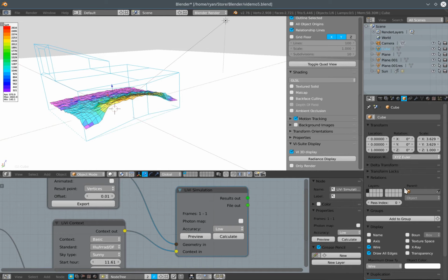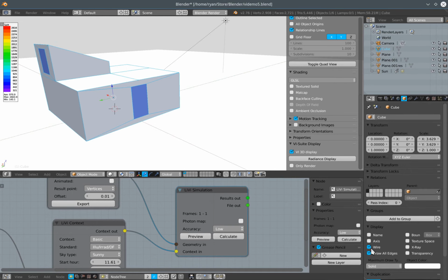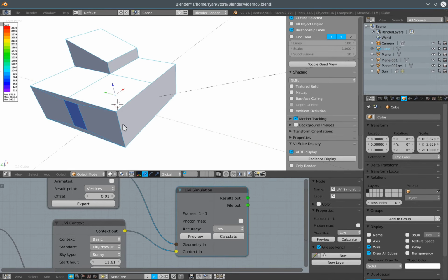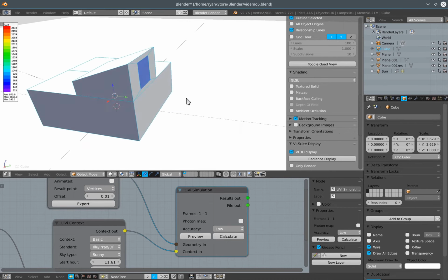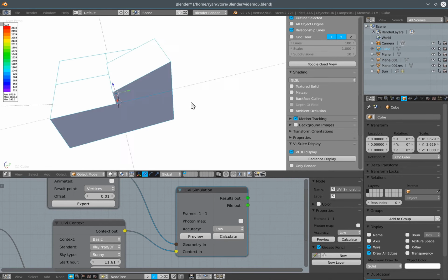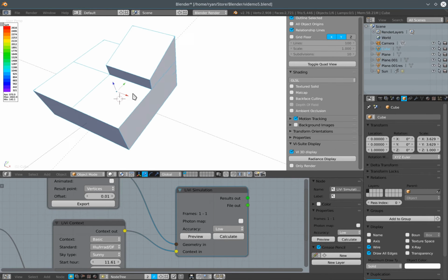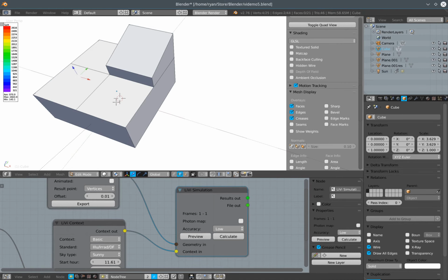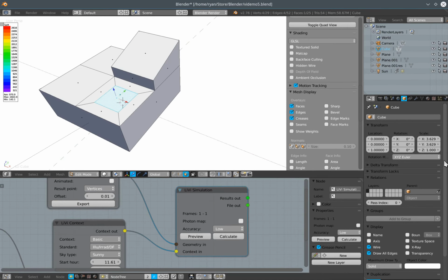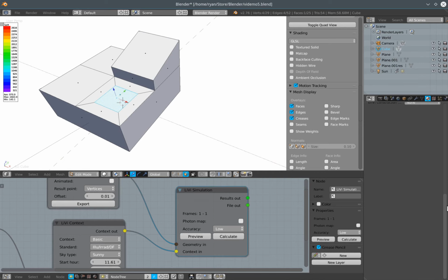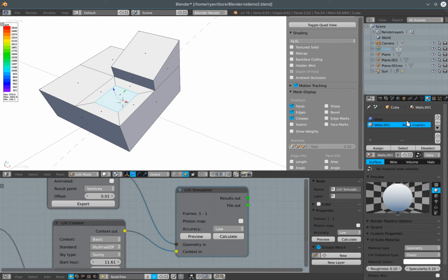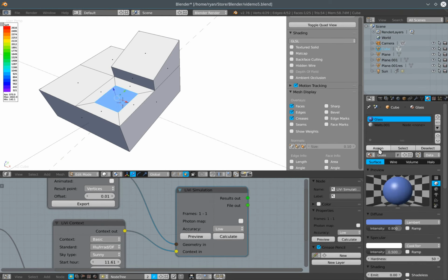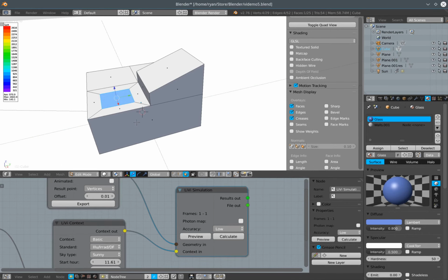So if I just put that building back in, I've now got a much narrower window. I might say I'm a little bit concerned that this window isn't producing that much light in my scene. So I might just create a new window in here. And again, within my material tab, I want to assign the glass material to that new face that I've created.